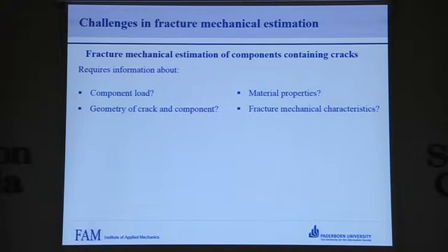The component load was the aspect which I studied within this research, because usually the component load changes during the service life of a structure. Consequently, the real component load is a result of different changing loadings, which can lead to retardation or acceleration effects in fatigue crack growth.